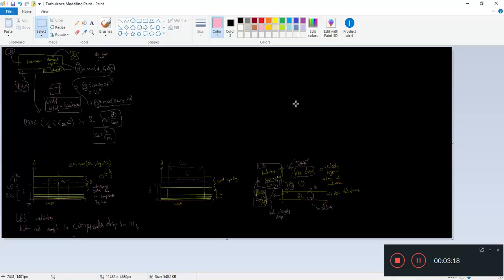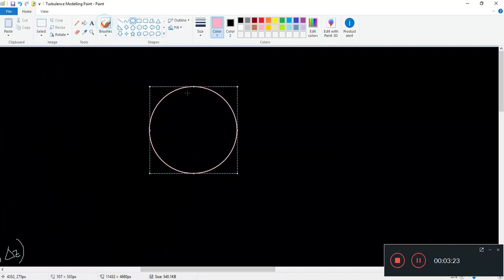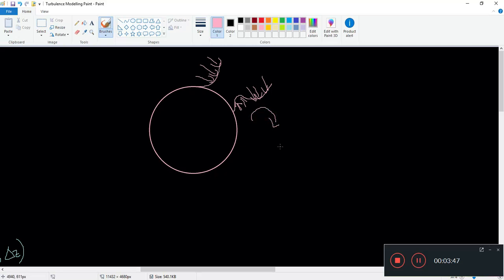Remember the classical case of flow separation. If you have a flow around a sphere, for example, then you have this flow here, and this is your velocity profile, and somewhere down the line the velocity profile will have this kind of opposite swirl. You'll have this swirling motion here. This is the flow separation we're talking about, where this part of the velocity starts to stall, slow down and then go in the opposite direction.